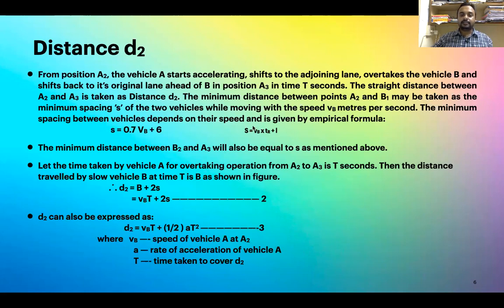So when the vehicle speed is in kilometer per hour, suppose 40 kilometer per hour, to convert it into meter per second, you will multiply it by 0.278. Okay, when you multiply 0.278 and consider a reaction time of 2.5, you will get 0.278 into, suppose 40 is in kilometer per hour. So when you multiply 0.278 into 40, that is the speed in meter per second actually. So automatically, though we are considering the speed at 40 kilometer per hour, since you are multiplying it by 0.278, it automatically gets converted into meter per second.